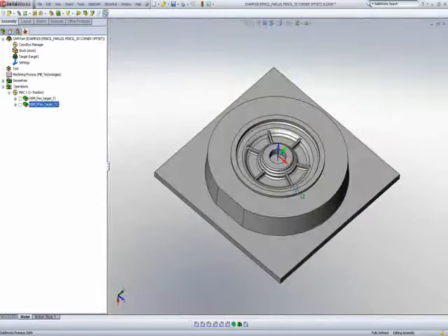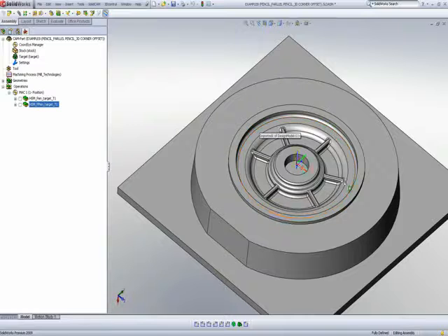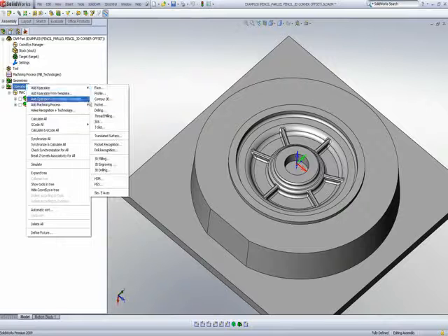Another option we can use here is something called 3D corner offset. Now what 3D corner offset does is very simple. These areas, the best way to work on these areas is with a 3D constant step over. But with a 3D constant step over, I have to usually pick out the boundaries myself. But with the 3D corner offset, we're actually allowing the program to use the pencil milling boundaries that it picks out all by itself and to automatically give me those boundaries and work within those areas using the technology of 3D constant step over.